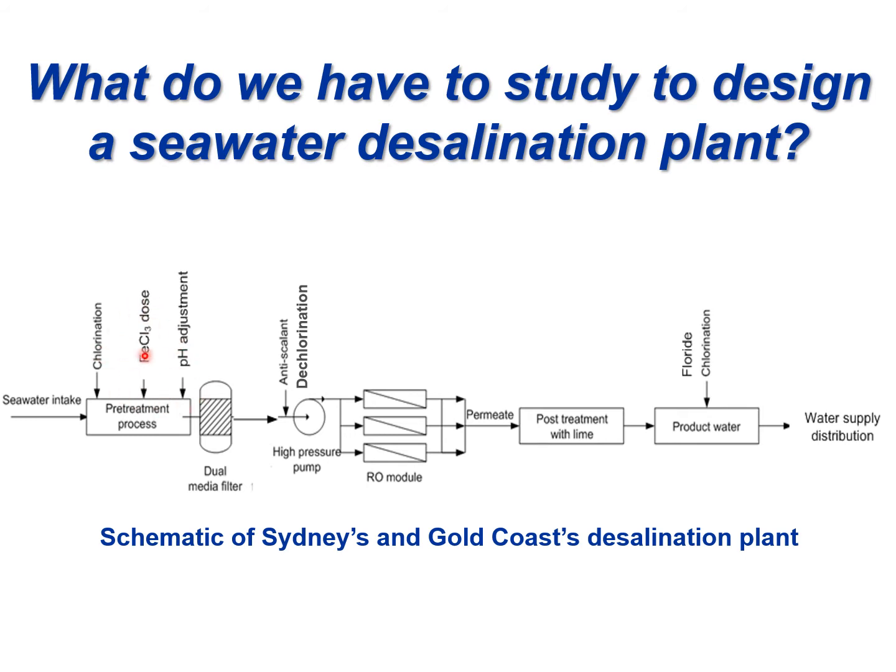And ferric chloride. So ferric chloride will be dosed, because large particles can influence this process, which will clog the media filter and reverse osmosis. So we want to remove the large particles. So flocculation using iron chloride, so we can try to